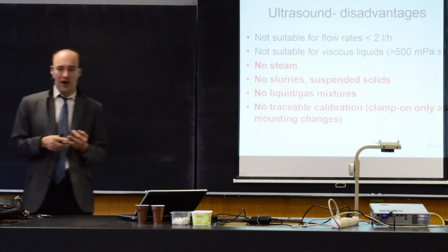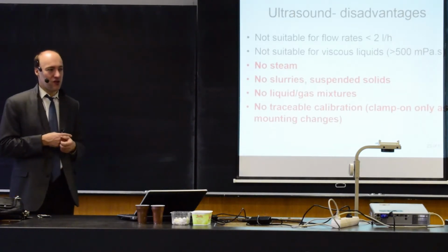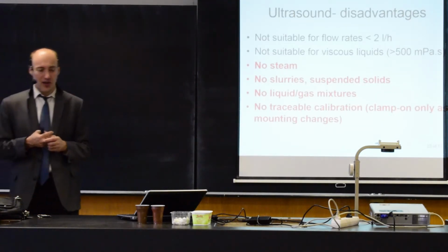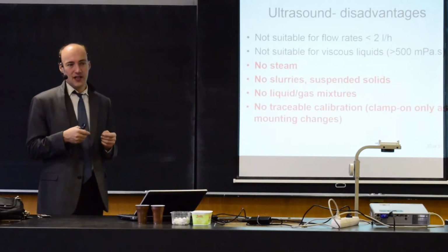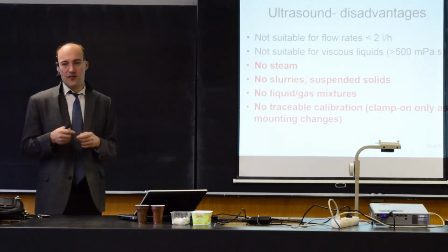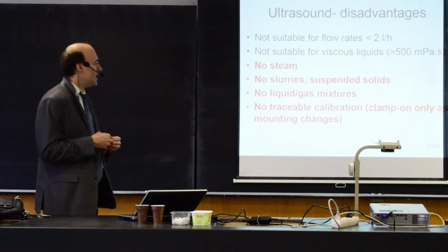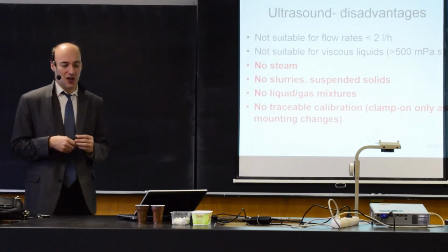And if you have the clamp-on system, there is no traceable calibration to a standard, because every time you install it, the installation is a little bit different, and hence you cannot trace it back for some calibration.